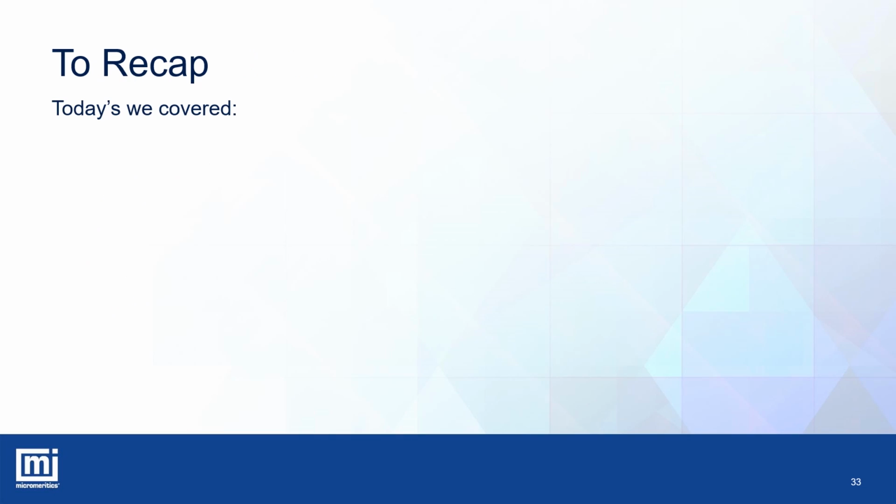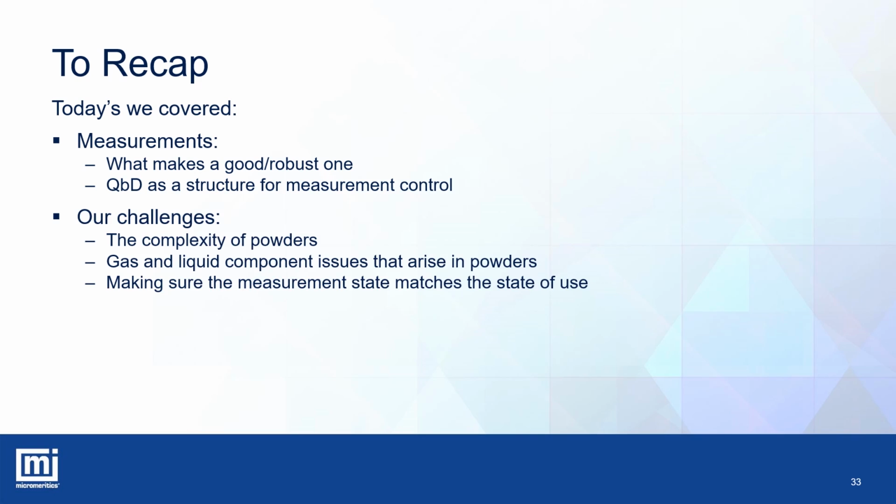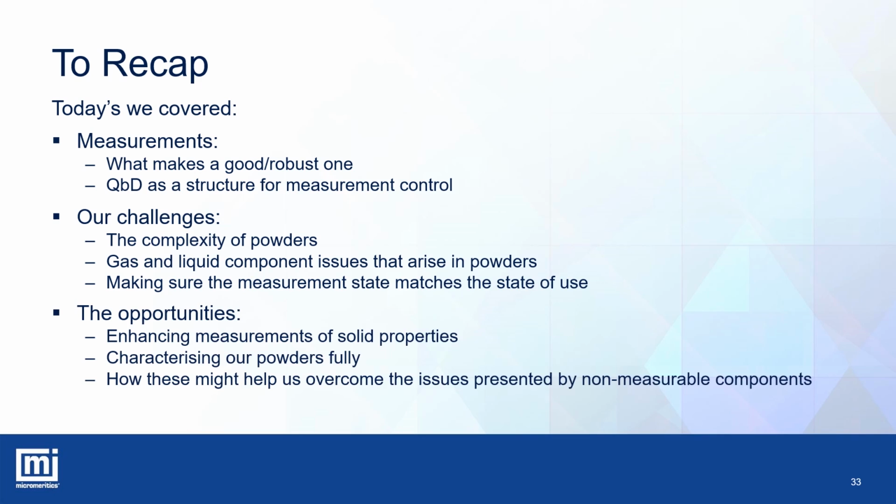Okay, to recap, I hope I've given you an understanding of measurements, what makes a good robust one, and QBD as a structure for measurement control. Our challenges: the complexity of powders, and how gas and liquid components can present issues. And also the need to make sure the measurement state matches the state of use. The opportunities: how we can enhance measurements of solid properties, and how to fully characterize powders, and how these two things might help us overcome the issues presented by non-measurable components.